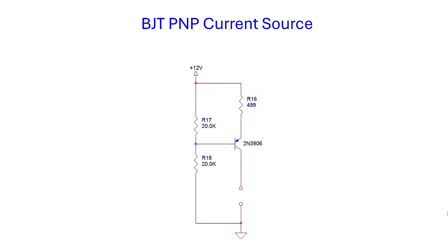The upper resistor is in parallel with the 499 ohm resistor, but because the transistor's emitter to base junction is also in the loop, the parallel resistance to the 20K ohm resistor will be equal to beta times the 499 ohms. For circuit analysis, assume that beta is equal to 250. Find the parallel resistance of 20K and 250 times 499 ohms. Use this parallel resistor value instead of the upper 20K resistor and calculate the base voltage using the voltage divider equation.